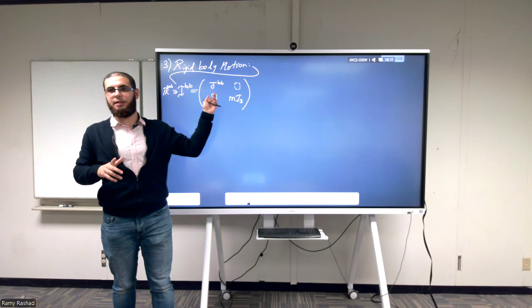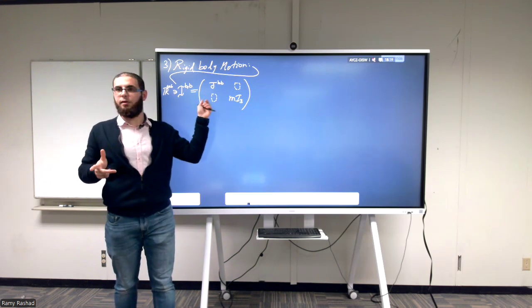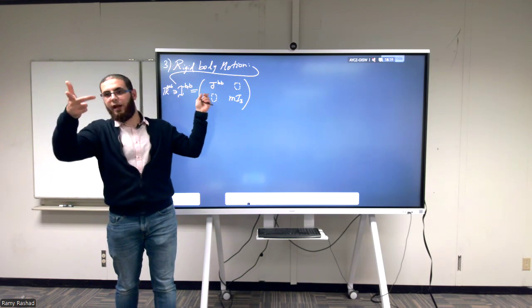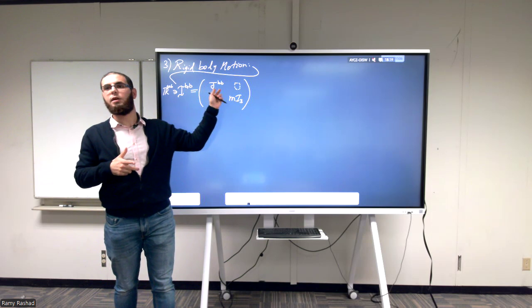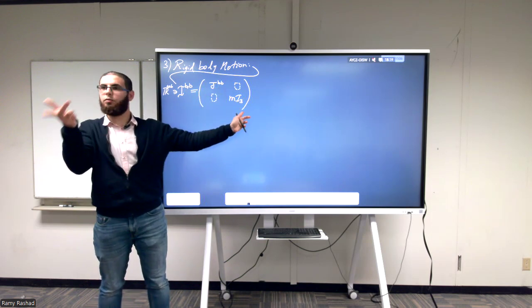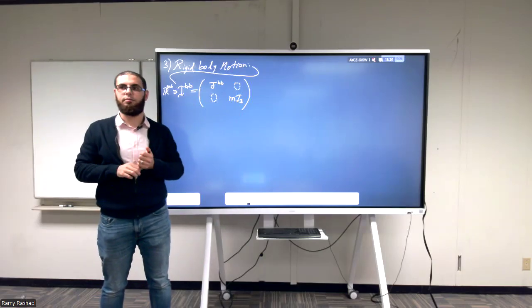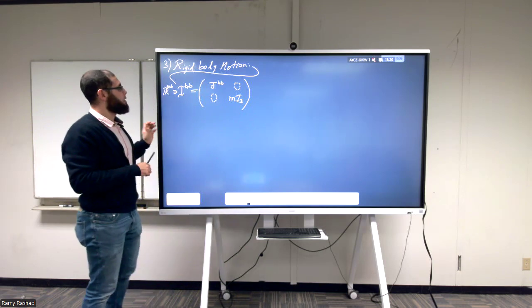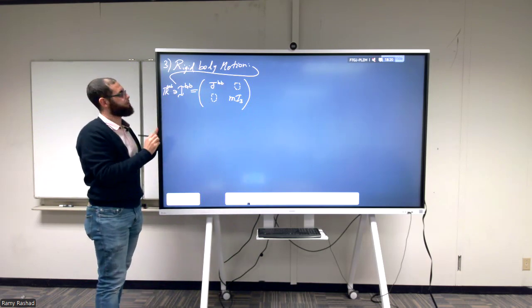This would be a 6x6 matrix. Put this frame on the center of mass, these two disappear. Align this frame with the principal axes of inertia, and this becomes diagonal. So in the end, this becomes a diagonal 6x6 matrix only if you choose the center of mass and align it in a certain way. But in general, it's a symmetric matrix like this. Let's keep it general.